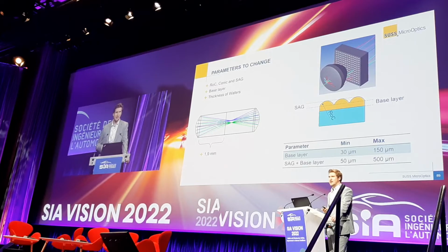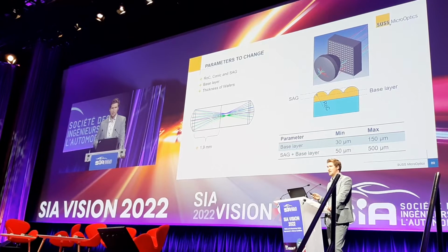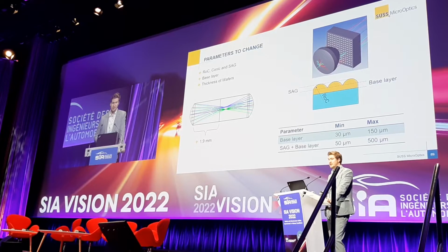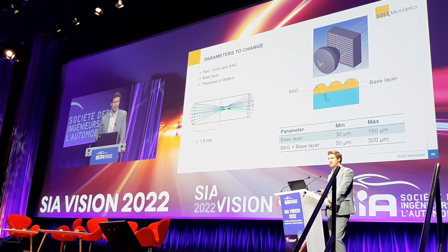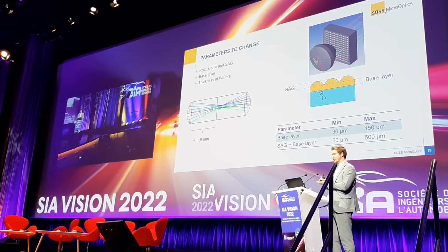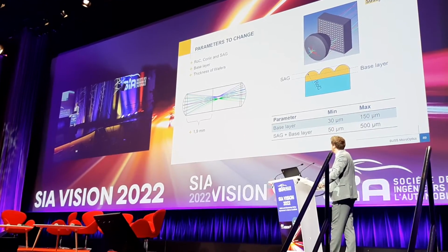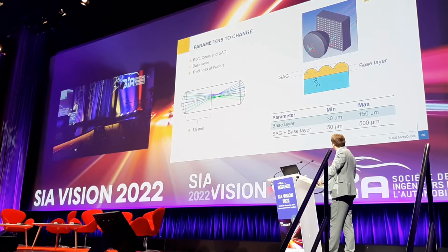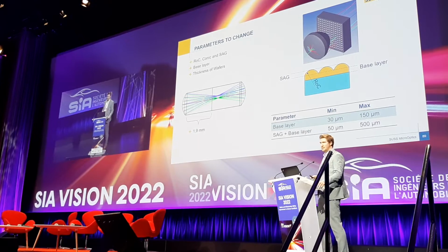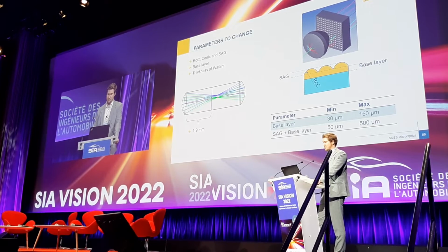And for the optical design, it's good to have a base layer between 30 and 150 microns, so 150 microns or 100 microns as a starting point is quite good. One can do variation on the wafer thickness, but the imprint process works best because the pressure aligned on the dies while doing the imprint can be regulated quite well. And together in the overall system, the second base layer should be up to 500 micrometers. When it's getting bigger, it's harder to get good results on the lens shape afterwards.